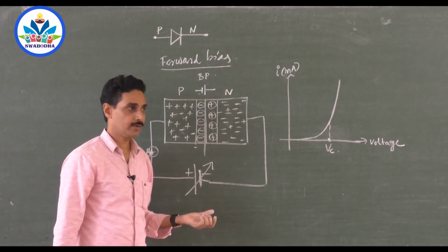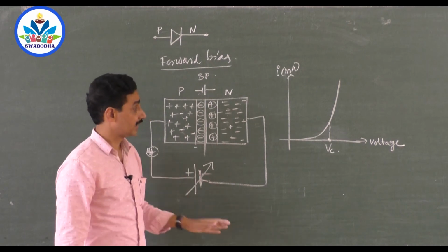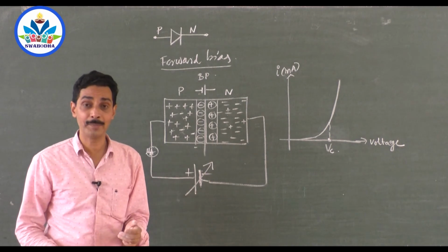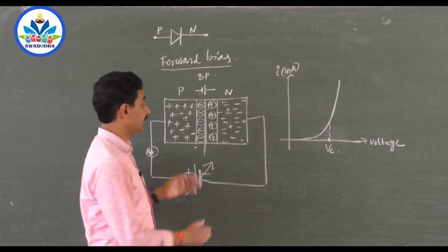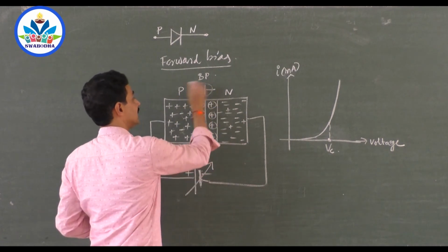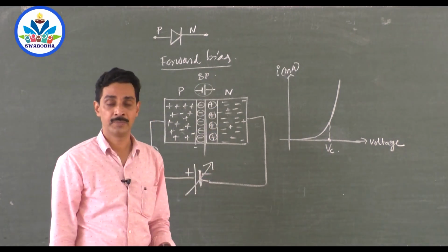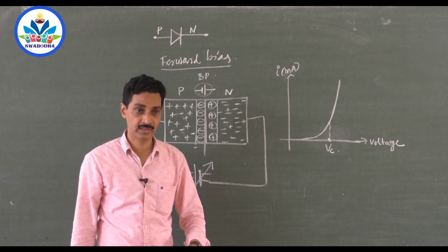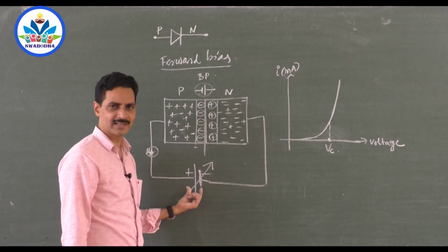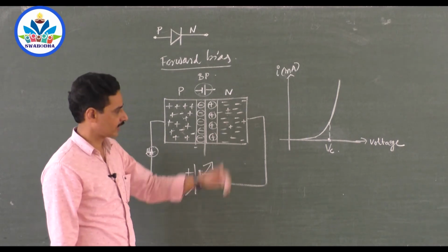And that forward bias voltage after which current rises sharply, because these electrons and holes are waiting for somebody to help them. And when the sufficient help is given, they can cross because they need not care about this barrier potential. The potential which avoids the migration of holes and electrons, that won't be carried by all these electrons and holes because they are getting support from somebody else, so they can cross the junction.